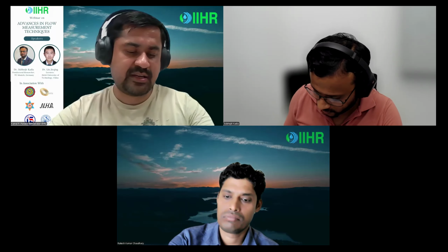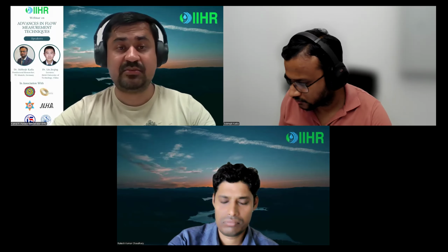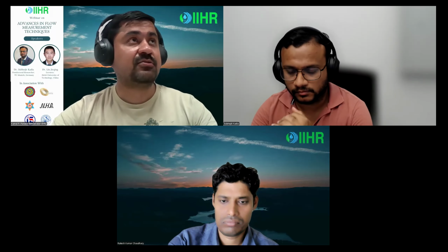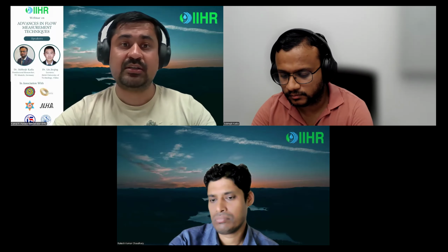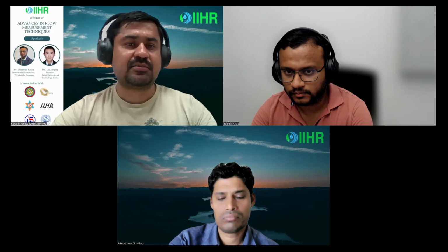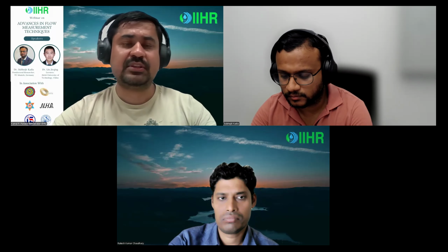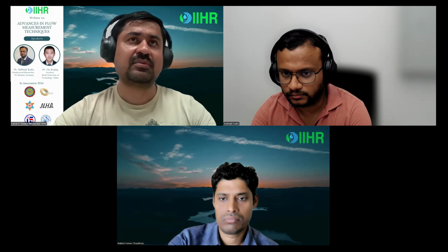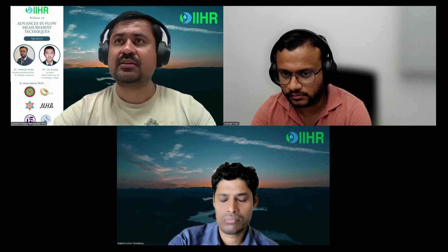And from the talk from the speaker on particle tracking velocimetry and particle image velocimetry, there are some advancements in the field regarding the field application of PIV as well as PTV. In case of PIV, we have seen some research where they have produced PIV techniques that can be used in the field, especially to monitor ecohydraulics. That means to monitor how the living organism dynamics play out in the aquatic habitat.